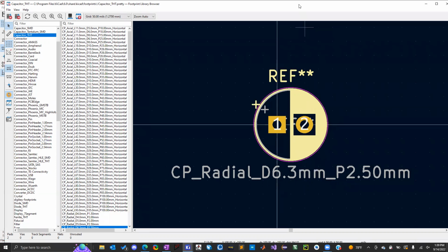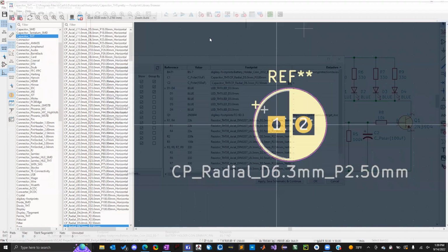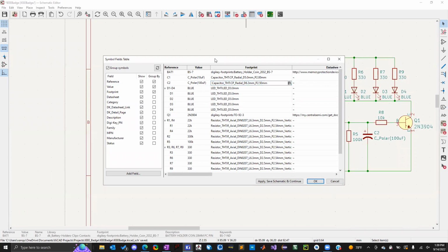All the components here that we're picking are pretty generic. Most manufacturers will be able to make this, but sometimes your symbol could break the rules that you've set for your board. And so you will have to actually pick a different footprint for your component because the manufacturer, maybe if it has like a 0.5 millimeter pitch, right?